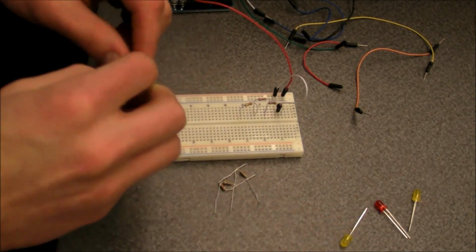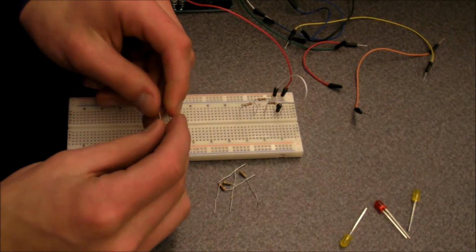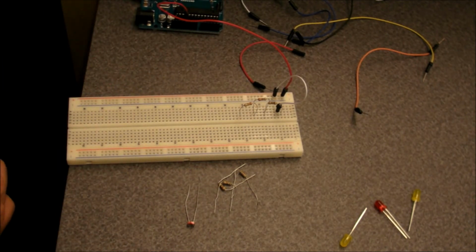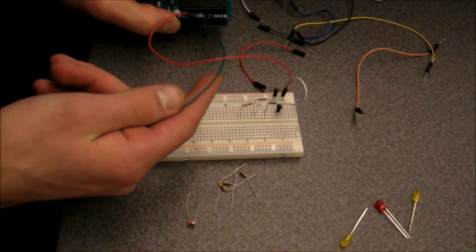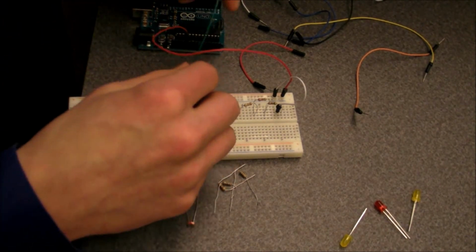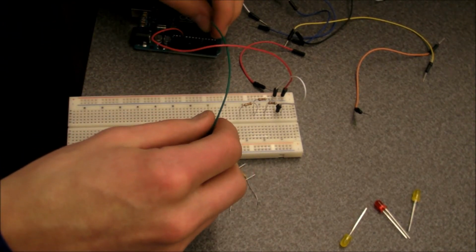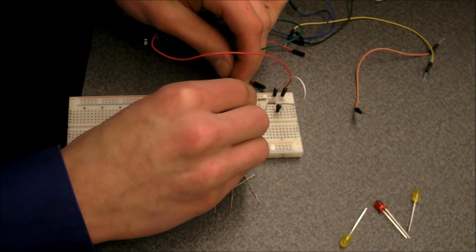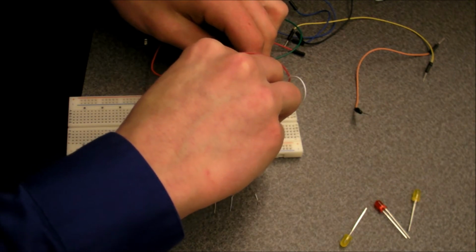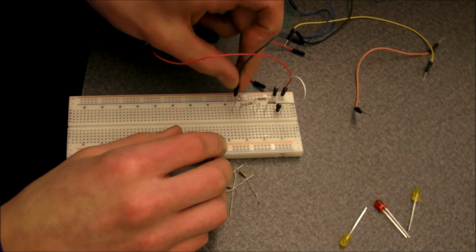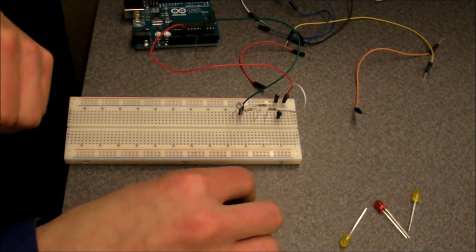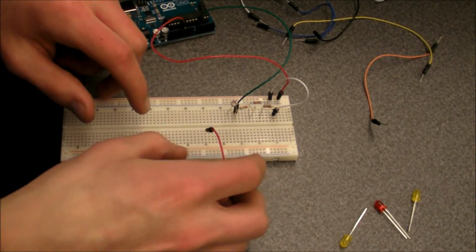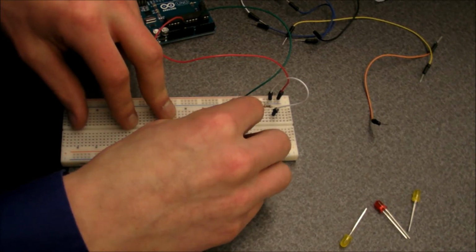here. Okay, and then since the Arduino will be reading from the light sensor, we will need to use one of the analog in pins, and so we will use A0 so it can receive readings from the light sensor, as we can see here, which will then, after the voltage passes through the light sensor, just go to ground, and we'll have ground be on the other side.